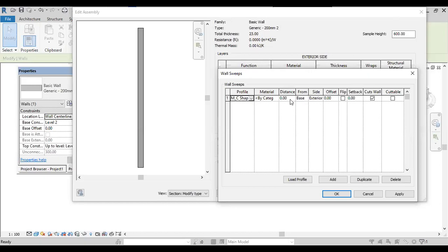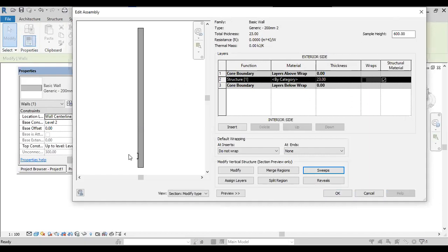Then you can set the distance. From the bottom, maybe I need this sweep with a distance of 50. You can input the material and all. In the case of material calculations or appearance also, whatever material you are using, you can apply that. Material is in our coming session only. Then apply. The system will show the shape.